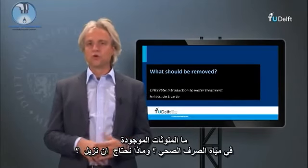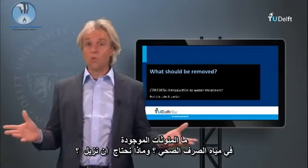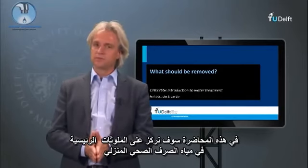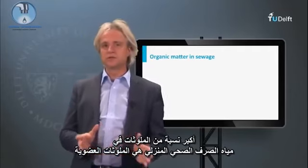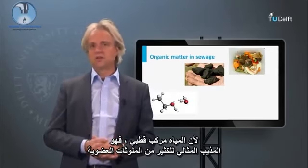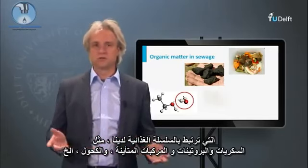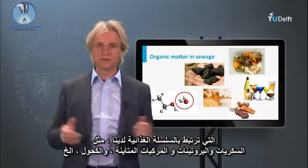What pollutants or contaminants are present in the sewage, and what do we need to remove, why, and to what extent? In this lecture, we will focus on the major pollutants in the domestic sewage. The largest fraction of contaminants in domestic sewage consists of organic pollutants. Since water is a polar compound, it's an ideal solvent for many organic pollutants that are associated to our food chain, such as sugars, proteins, ionized compounds, alcohol, etc.